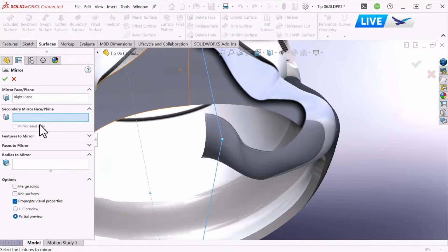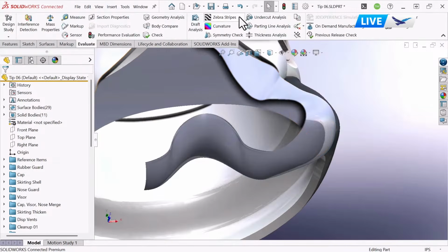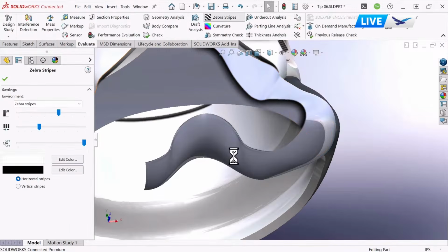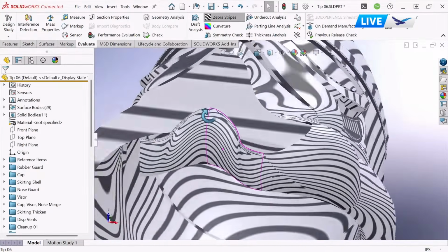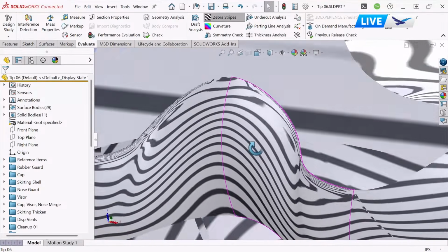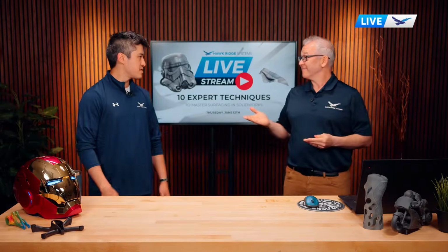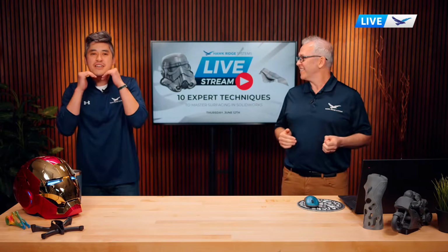Yeah. And I think this also brings up a side point. When we're thinking everything needs to be really smoothly connected, we need this continuity, there's this feeling of always needing to use the highest level, the always crank it up to 11 kind of problem. Yes. And that's definitely not true. Sometimes tangency to face works better than curvature to face. You can get something better. And maybe you want a little cleft. Yeah, if you don't have it, then you can have a little cleft.